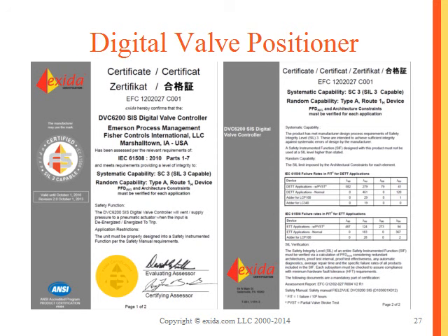And how do we know that? Because we go into that product, we evaluate the product in detail, look at each and every one of the components, and then we look at what if a partial stroke test happens. Will we detect this particular product failure, this particular component failure? And if so, then obviously it's a detected failure. If not, it remains an undetected failure.